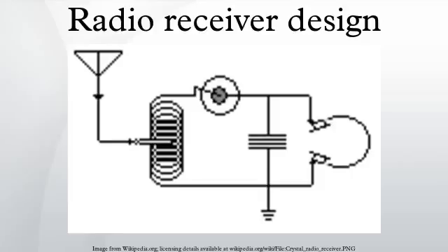From the accompanying schematic for a practical regenerative receiver, one can appreciate its simplicity in relation to a multi-stage TRF receiver, while able to achieve the same level of amplification through the use of positive feedback.